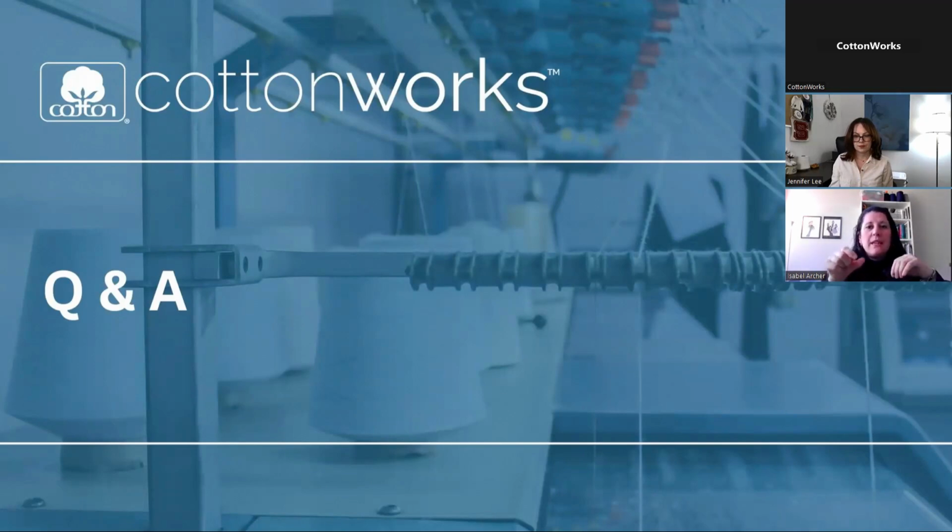So it's a 14 gauge machine. But when you use every other needle, it's a 7 gauge. So certain companies call that a 7.2. But virtually all machines can do multi-gauging, but it's just basically half the number of needles of your gauge. You can multi-gauge between the two of those.